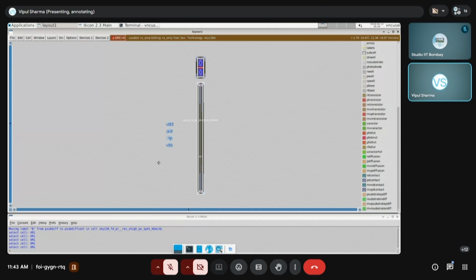And these are the pins. These pins again come from the schematic in the netlist because we have defined these pins. So right now we only have these two components. But I can see this NMOS is not looking proper. It has a very big width. I would like to divide it into separate fingers. So how to do that?